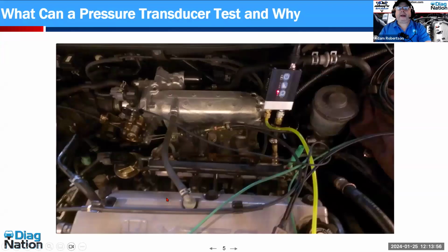Yes, I can measure fuel drop by the hydraulic vibration. Before some of you get carried away, let me clarify something. I have done a lot of this style testing over the years, and for those of you who think this test is going to be accurate enough to determine if an injector is slightly low on flow or not, it simply is not. That is still a situation where the injectors would need to be pulled out and tested physically on a test bench.